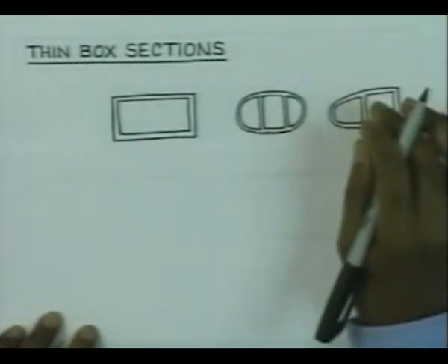So, this type of sections are utilized in the case of machine tools bed and also aircraft wings, although we have other applications too. When these sections are subjected to torsion, particularly in the case of aircraft, when the wind thrust is not uniformly distributed at the bottom of the wing, you will find that some amount of twisting comes up on the section, and it is necessary to evaluate the magnitude of the stresses.